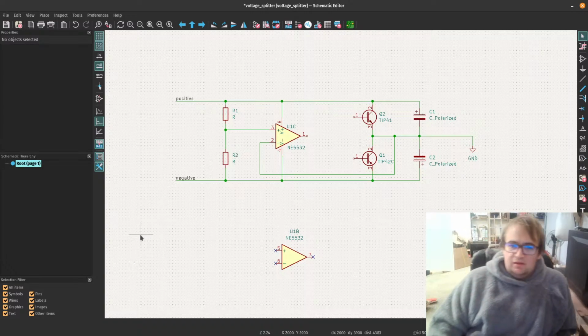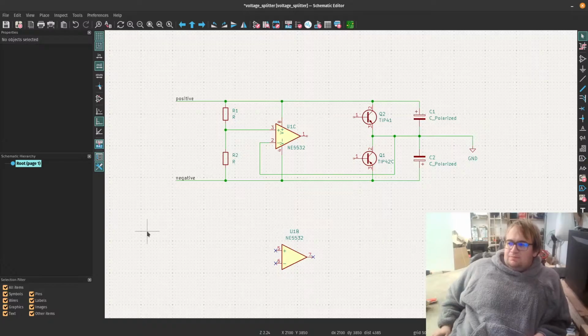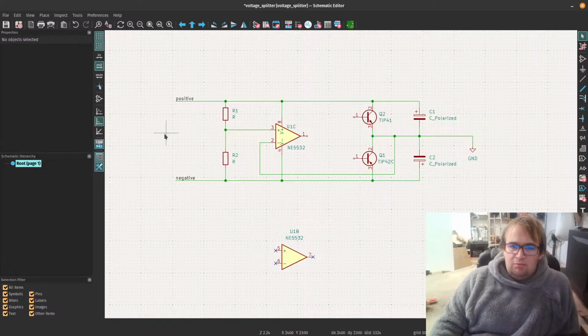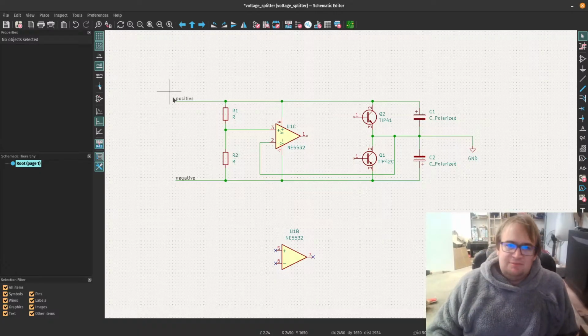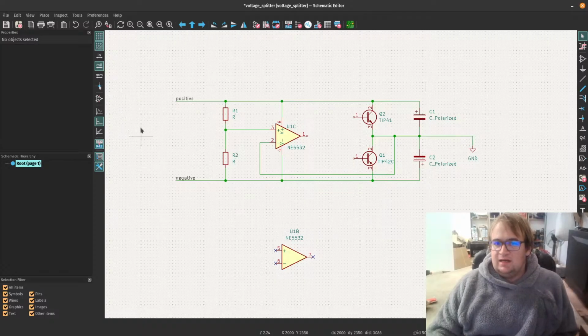So you see what I was saying again. Basically, this is where I connect my power supply, positive and negative terminals. Then I connect its ground here. And what I'm probably going to do now is actually make a connector right on this side. So like if this was the PCB, there will be one connector here and another connector over here.